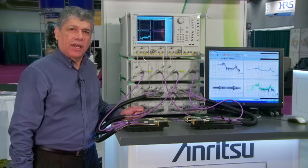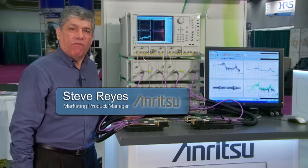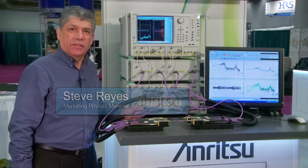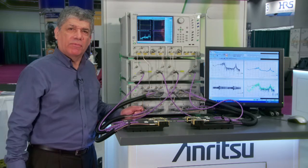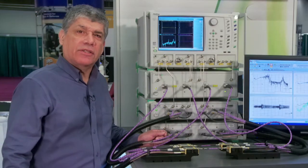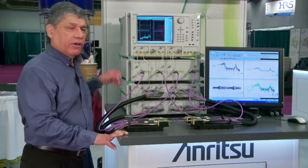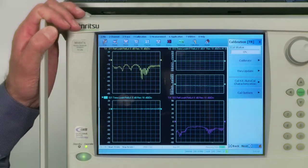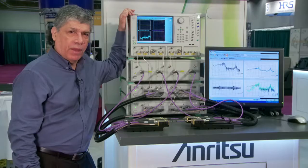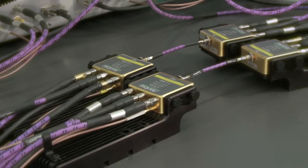What I'm showing here is a 4-port VectorStar broadband system. The 4-port system is the same broadband system operating from 70 kilohertz to 110 gigahertz, except in this case we're using 4 of our Anritsu millimeter wave modules instead of the 2 for a 2-port configuration. The VectorStar is the 70 kilohertz to 70 gigahertz version. And then we have a test set that drives the millimeter wave modules.